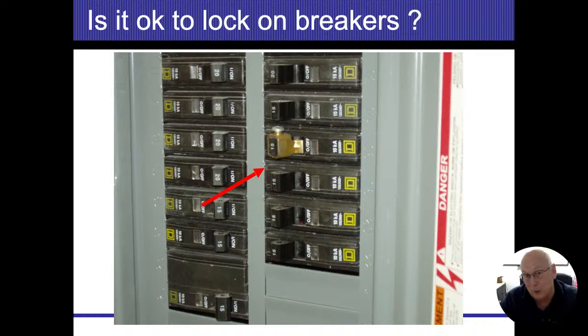And even, you know, they have lockout tagout kits. And now it shouldn't be locked in the off position. If it is, chances are good there might be somebody working on a system somewhere, and he locked it off so that nobody can turn it on by accident. I would obviously investigate that.